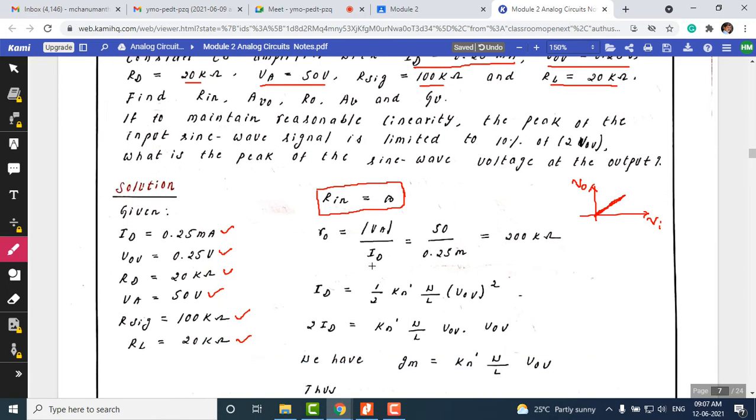Next, let us see some formulas. We might not derive them, but you need to be aware of them. You should remember that. Write down these formulas at the end of your notes so that you don't forget while solving the problem. This is a relationship between the MOSFET output resistance, the early voltage and the drain current. So R naught is equal to modulus of VA by ID. This is the equation which you need to remember. Again, this comes under the fundamentals of MOSFET, though it's not there in the syllabus, so you need to remember this type of equation.